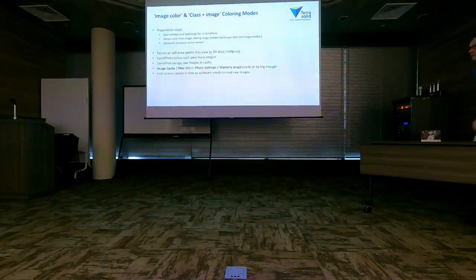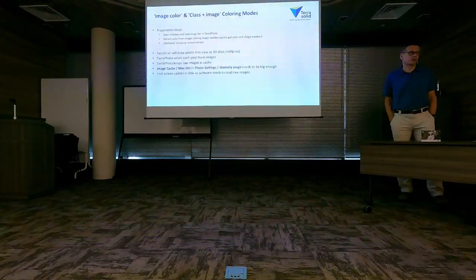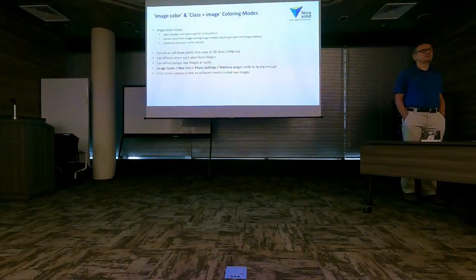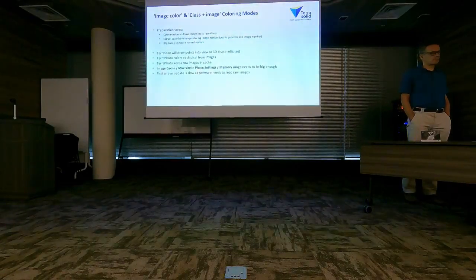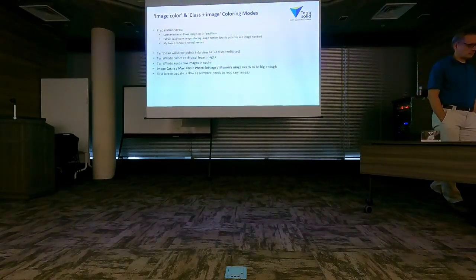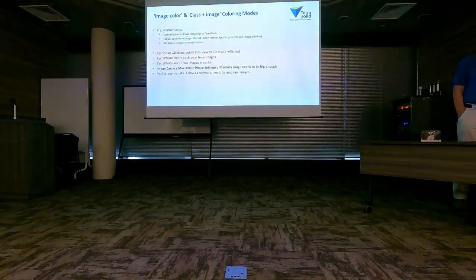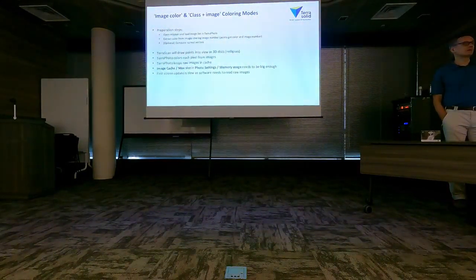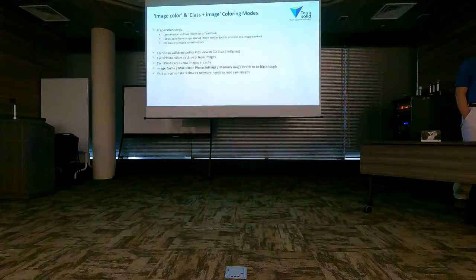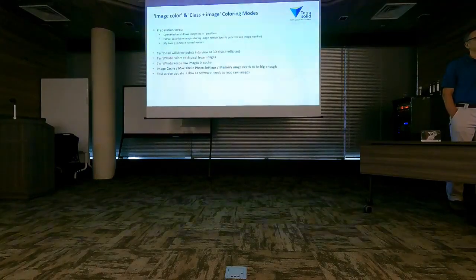And for this to work, you need to have both TerraScan and TerraPhoto running. And you have to have a mission open and an image list open in TerraPhoto. And you must have done extract color, which gets a color value from an image to each laser point.